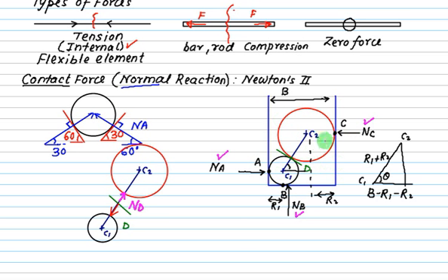No question about this one, because this is a non-concurrent force system. This is one interaction, this is second interaction. How many governing equations do we have? This is two-dimensional. So we have sigma Fx equals 0, sigma Fy equals 0. There is no question of sigma Fz, and only one equation is available in the moment, that is moment about z-axis is 0. So in a plane motion, we have three controlling equations: sigma Fx 0, sigma Fy 0, and moment 0. So you apply these equations and you are very well able to solve this.